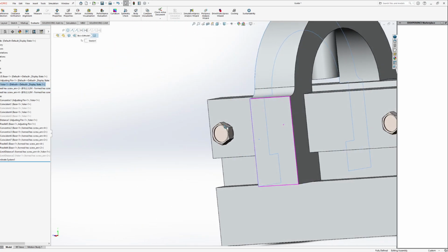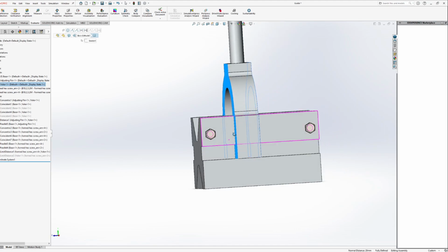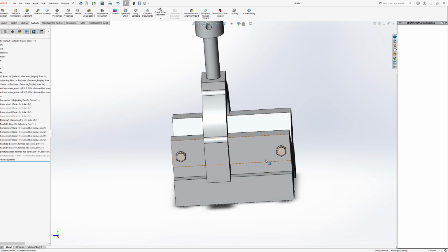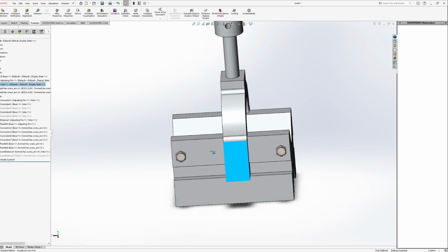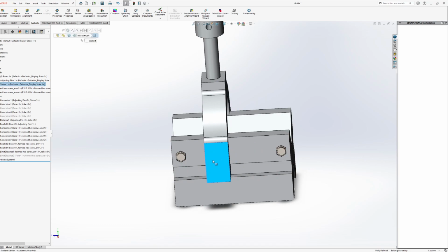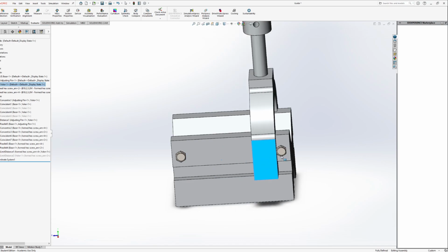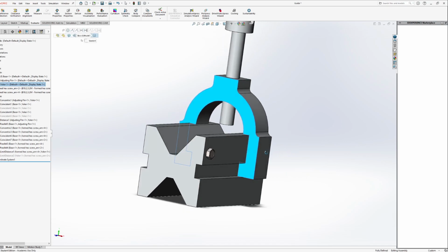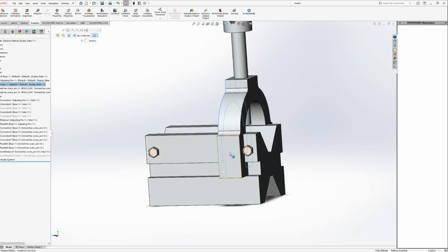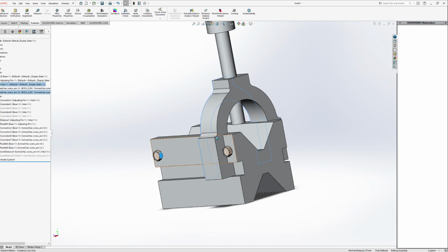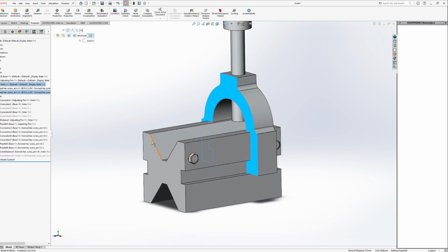If I incorporate how the yoke is taking up 20 of those millimeters, it's really just an exercise in wholes and parts. We have a whole of 77 and we have one of our parts being 20 millimeters. That means that there's only 57 millimeters of leeway that can ever exist here. So it's just up to saying, what's the maximum distance that this could possibly be without creating overlapping geometry? And that's really how I did it, at least in this instance.